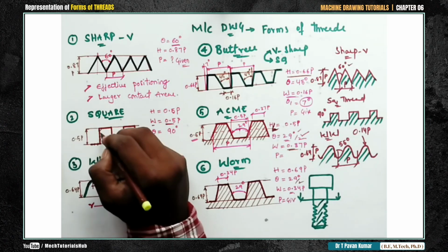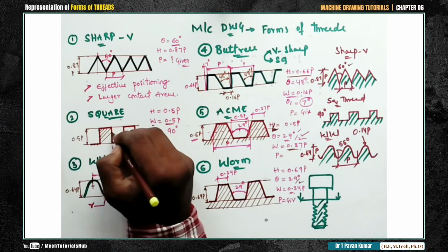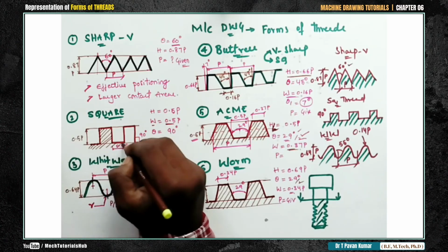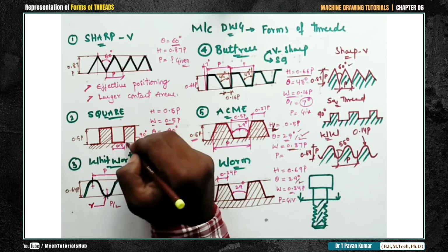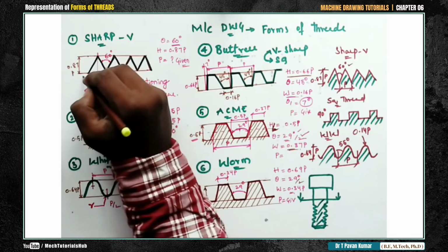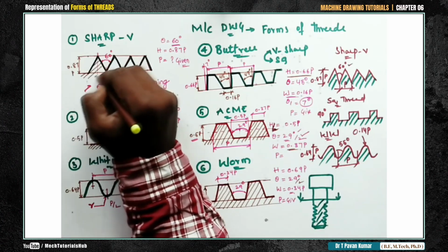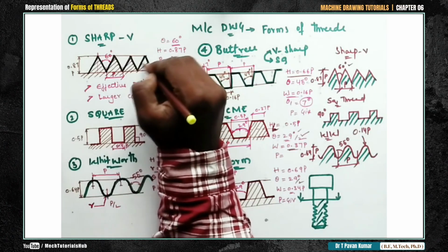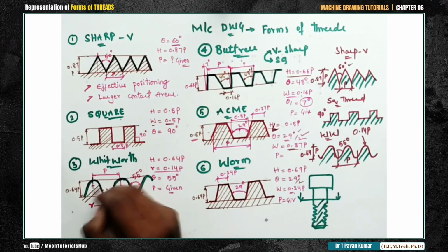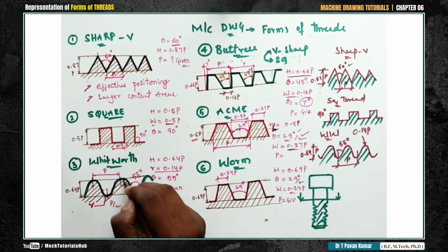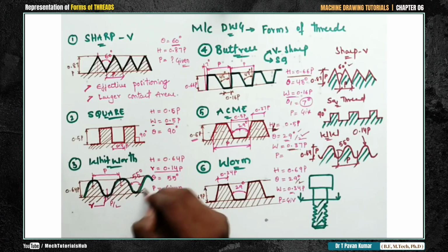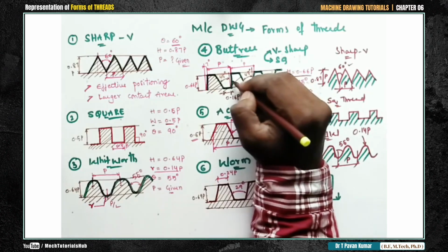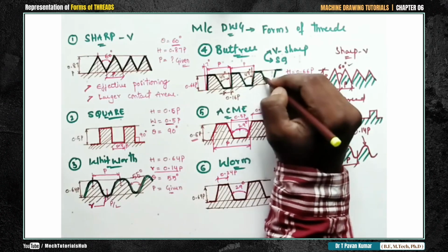This is also important. It should be drawn with a 2H pencil. There should be proper uniformity between the lines. The proper angle needs to be maintained all the time, okay. If you are not getting it properly, try to make markings of offset distance 2 mm, 4 mm, 6 mm, okay, 45. As I am somewhat free with my hand, I am trying to maintain that offset properly. Most of you are not used to it, so kindly make markings initially, then go ahead with your drafter maintaining 45 degrees inclination.